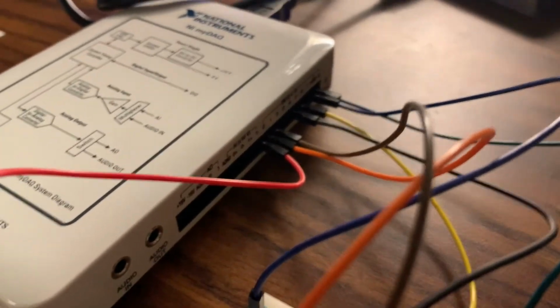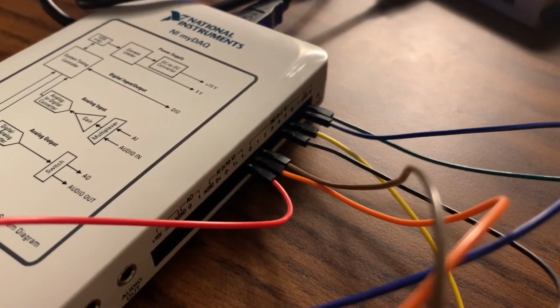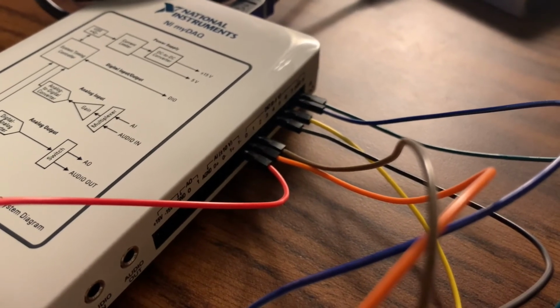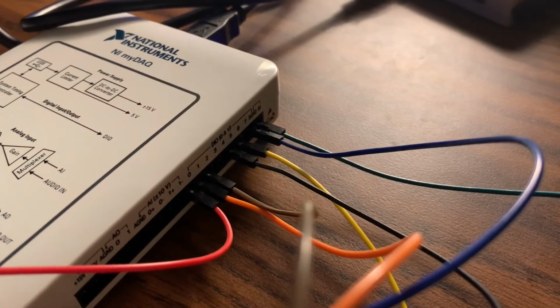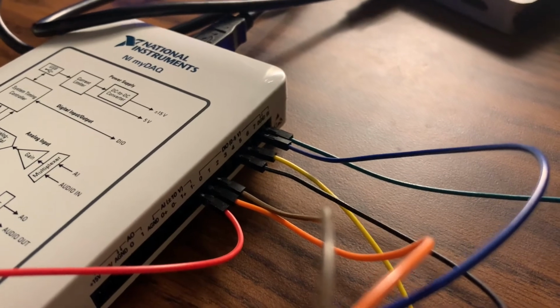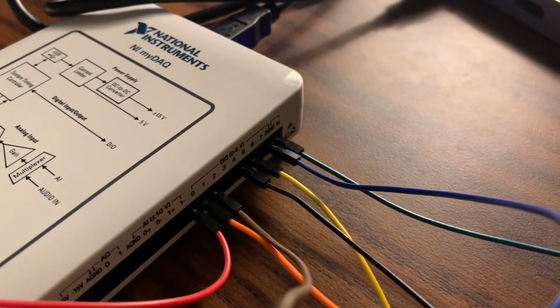So here we have pin 0 hooked up to A0 input on the decoder. Pin 1 is hooked up to the clock signals on the D flip-flops, and pin 2 is hooked up to the clear bar on those flip-flops. And pins 6 and 5 are equivalent to S1 and S0 respectively.